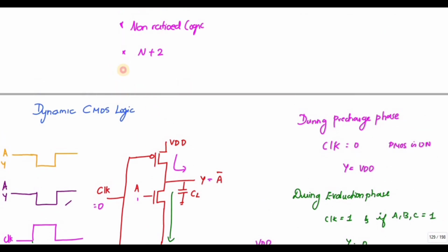So during the evaluation phase, if the NMOS conducts, then my Y goes to 0.